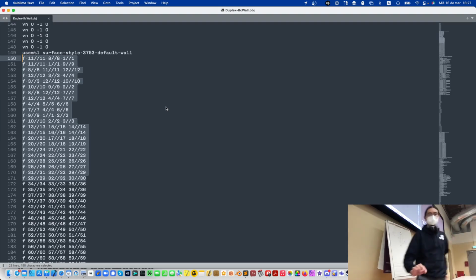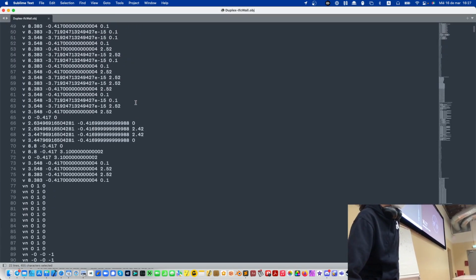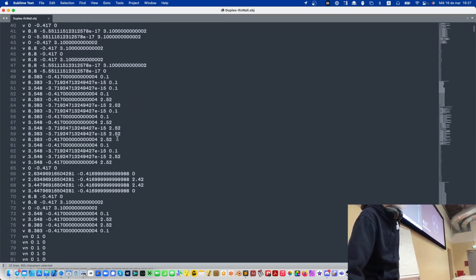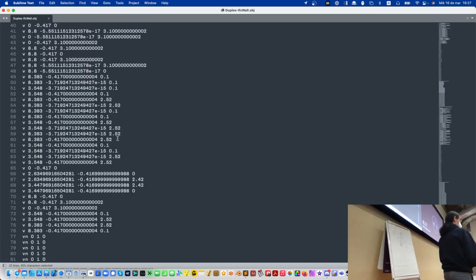Instead, what you find in practice is that some of the vertices have exactly the same coordinates, but each index of the vertices is only used once. If you pass this to the incremental builder, it will not connect things together. So you need to have unique vertices for the Polyhedron incremental builder in CGAL to work.